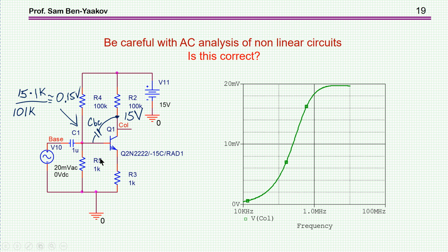So the point is that although the circuit is really represented by the small signal, and it's being analyzed, and the solution is correct, this is not what the designer probably intended, because it might have an error in one of the resistors. Therefore, one has to be extremely careful that the operating point is indeed correct, such that the linearization is around the correct operating point and not some obscure point that has nothing to do with the intention of the design.